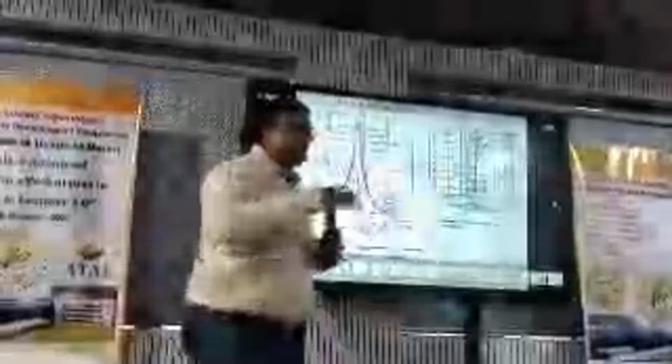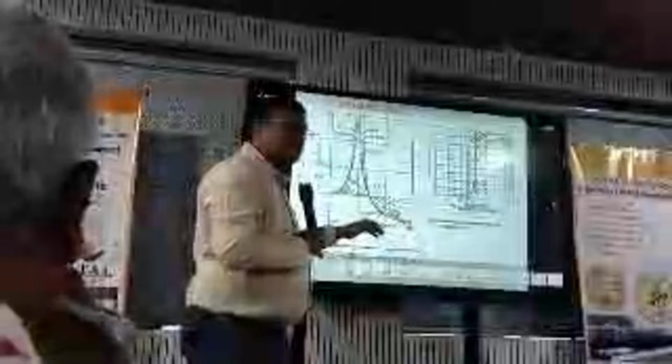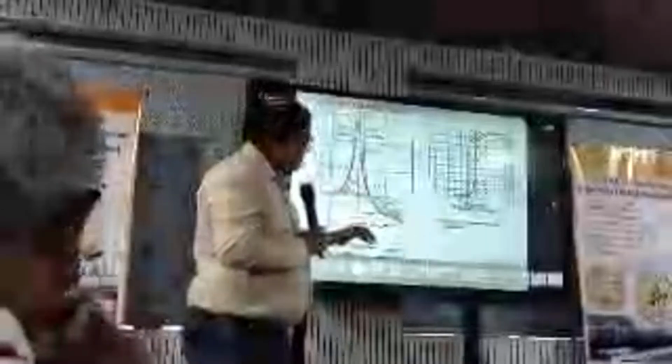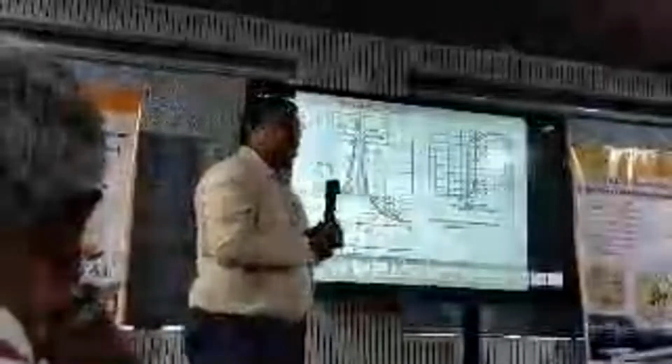Even though we will get higher vibration amplitude, if you separate the excitation frequency and natural frequency a lot, say 2000 RPM is the natural frequency, that is assumed, and the equipment is designed for 6000 RPM, then there is a very large gap and our machines won't be destroyed.